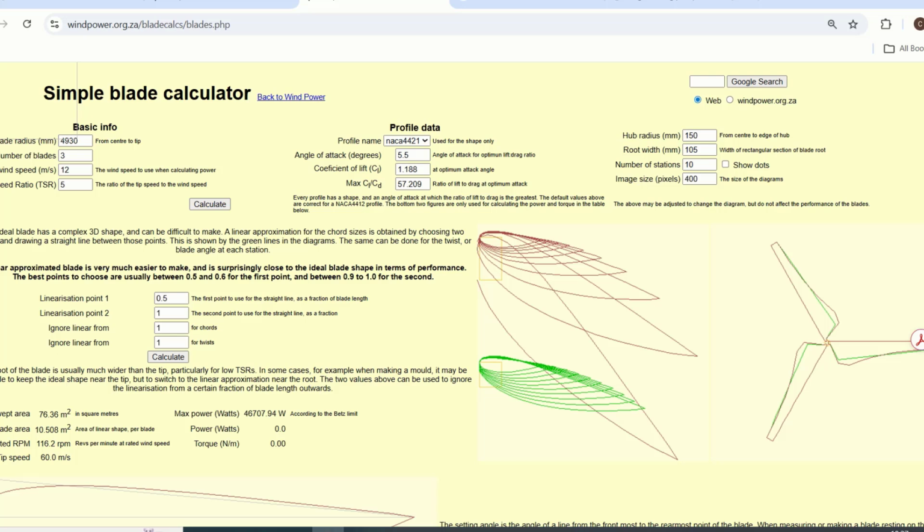And once you've selected that airfoil and optimized it, you are then able to switch it with other airfoils and use method 2, in which case you are optimizing for the angle, the lift and the drag. Once you optimize the aerodynamics for lift and drag, you are then able to use a wind tunnel assessment in order to find airfoils that result in twists that are not too large, that will make it easier to construct such a wind turbine blade cross section.